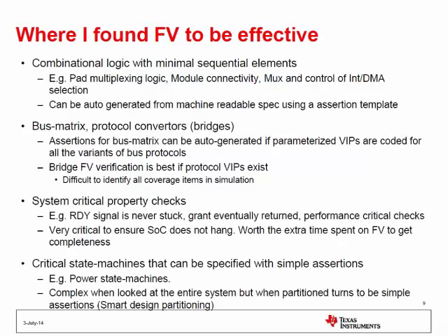Yeah, system critical checks. This is another area where I have found it very useful, because hang cases in the system are completely no-no. You will also see that it is not difficult to write some of these properties. All you need to say is that ready is not hung under a certain condition, and you can let the tool run as long as it wants, because there are very few properties you are trying to check. And this is, again, a very critical area for your whole SoC. If the system is getting hung, then it is a problem. If you make an access, or the way the bus matrix makes an access, if I'm just switching between multiple IPs and so on, you need to make sure that your ready is not hung.